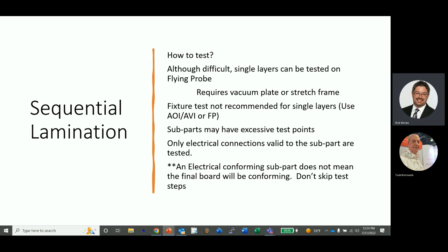So when you generate test points, you can take Class C, IPC 9252 Class C, everything open and mask. There's no mask, so we're going to test everything on this board. So if you have a landing pad somewhere or you have copper traces that go from point A to point B, you can put test points on the end of them. You can run your midpoint optimization.